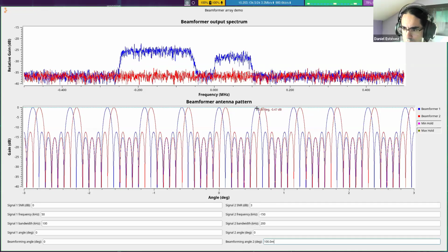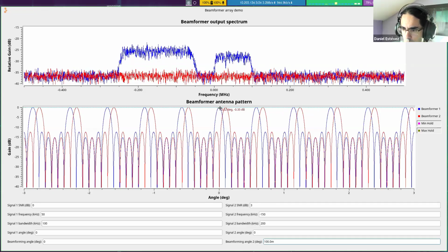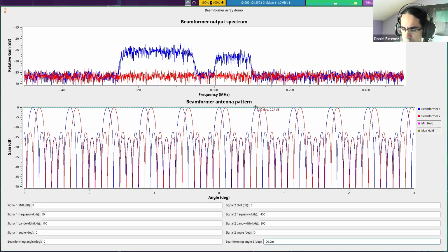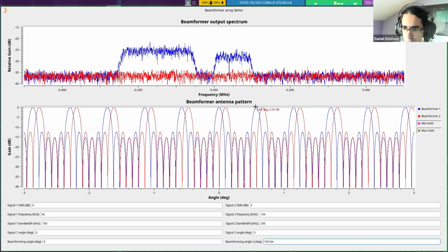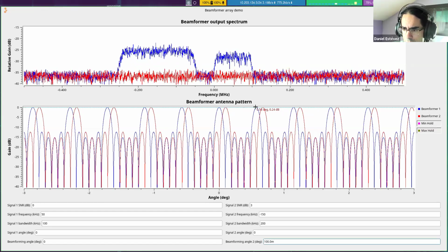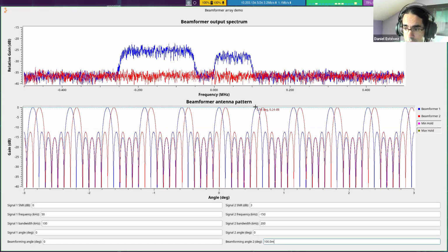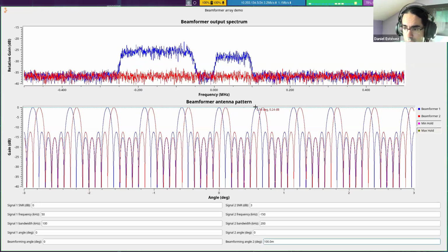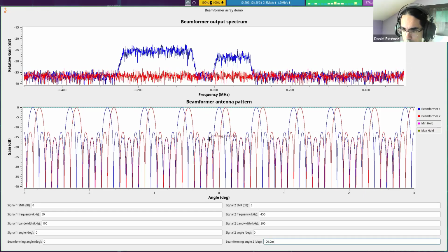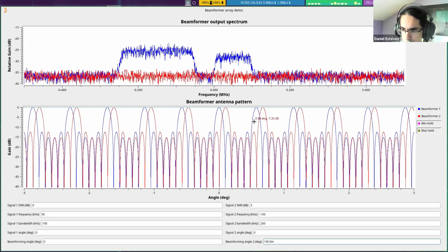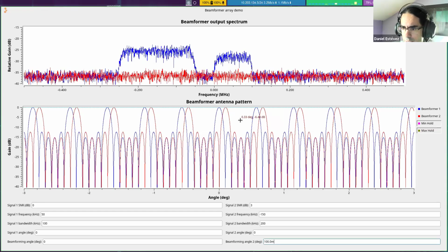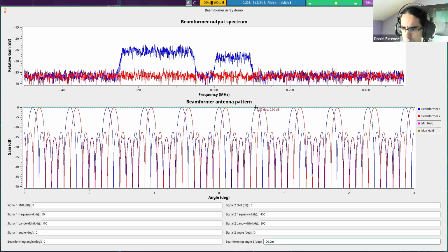Something important about this particular array is that whenever we point to 0 degrees, we are also pointing to something like 0.57 degrees. Maybe 0.57 degrees is already outside of our primary antenna field of view. For example, that would be the case with the Allen Telescope Array antennas at high frequencies. The antennas will always see this part of the directions, and these would be greatly attenuated by the dish antenna pattern. But if we have omnidirectional antennas, we will also see this direction.